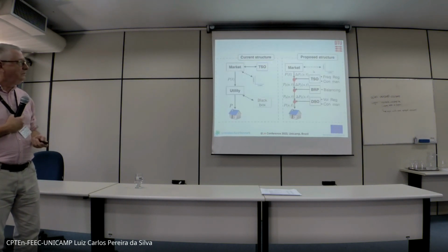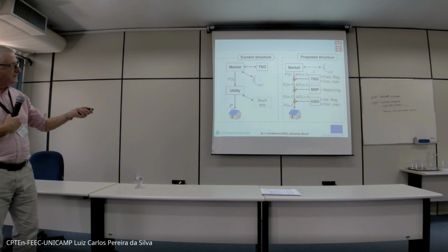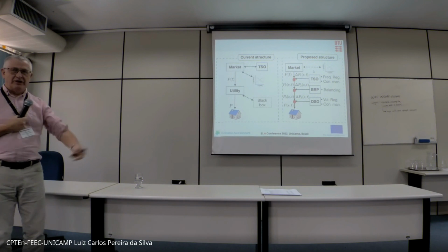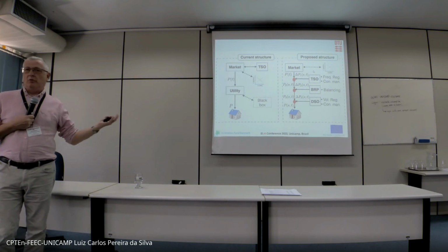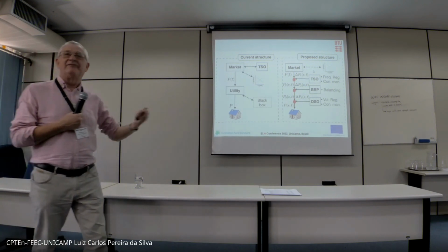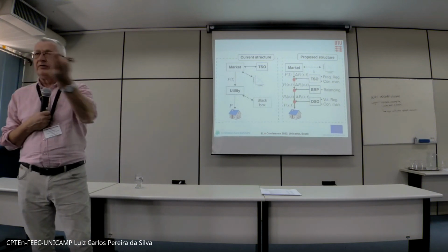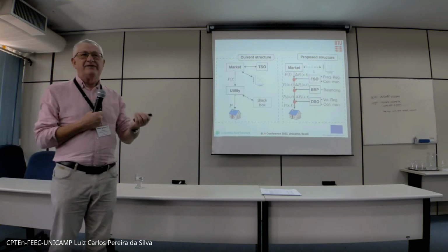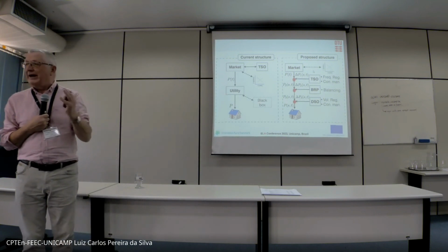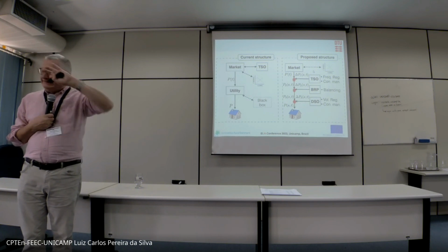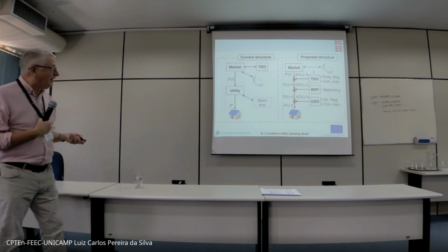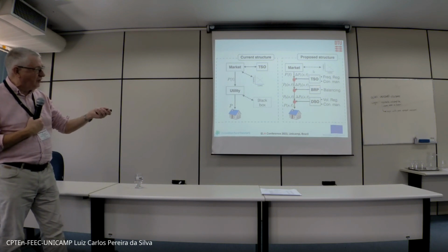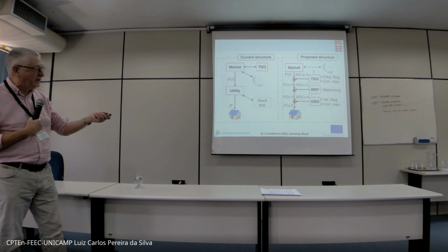for the TSO. The conventional setting is this market bidding with price bidding and so on. And then what happens on the DSO level is more or less a black box, as we also heard yesterday. It's difficult to see. We saw some very interesting discussions yesterday where we are getting a little insight into what happens. But the way it's operated today is more or less like a black box. Instead, we suggest this control problem, solving frequency, voltage, balancing, and so on.